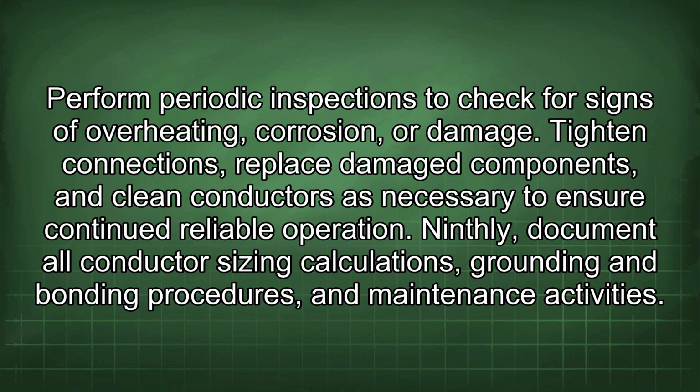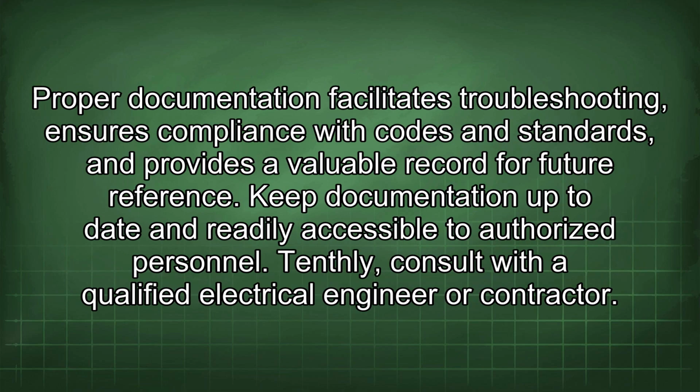Ninthly, document all conductor sizing calculations, grounding and bonding procedures, and maintenance activities. Proper documentation facilitates troubleshooting, ensures compliance with codes and standards, and provides a valuable record for future reference.